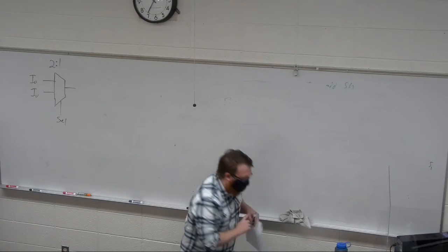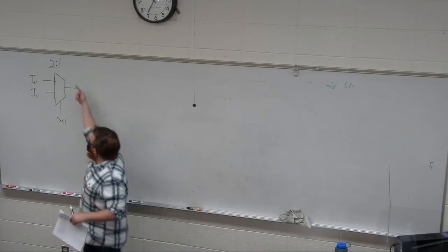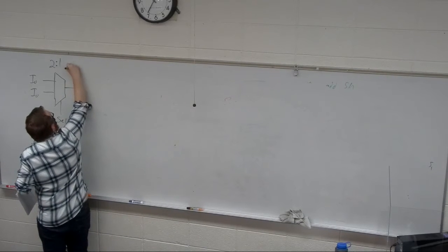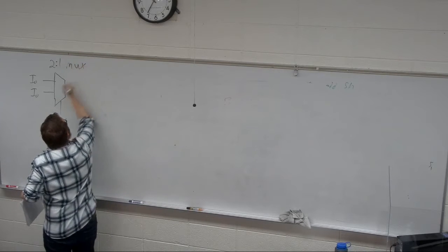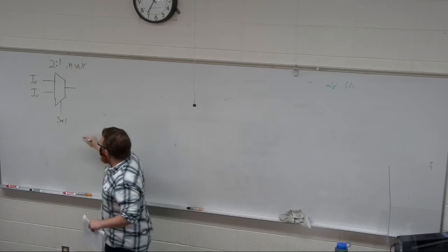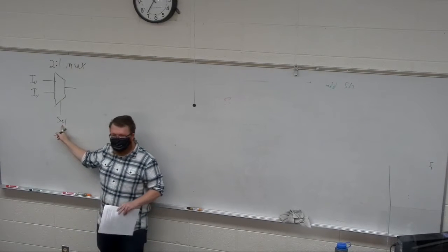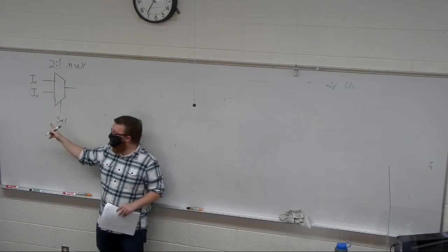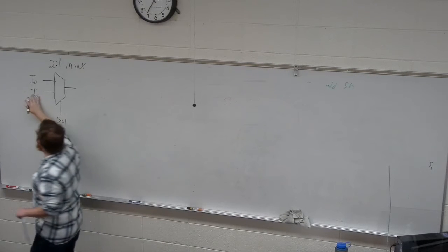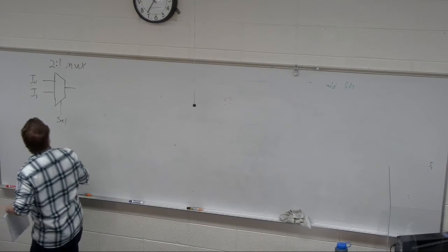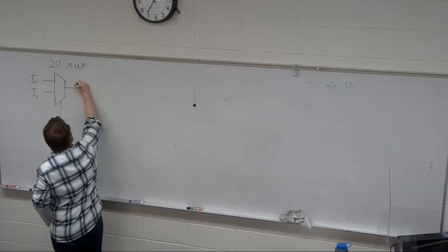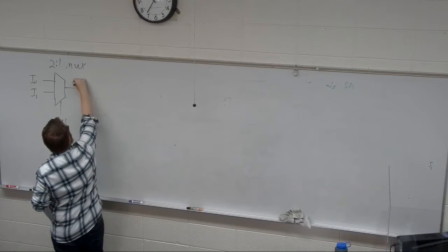Okay, there we go. All right, so this is what we would just call a 2-to-1 multiplexer, or mux. Now, all this is saying is select in a 2-to-1 is 0 or 1, right? So if it's 0, I take I0. If it's 1, I take, oops, this is I1. And then it's going to have some output, I don't know, let's just call it X.